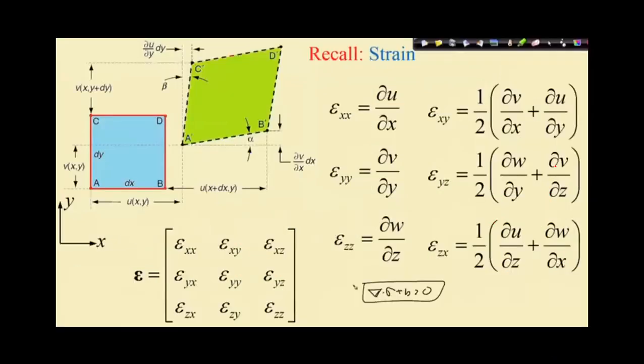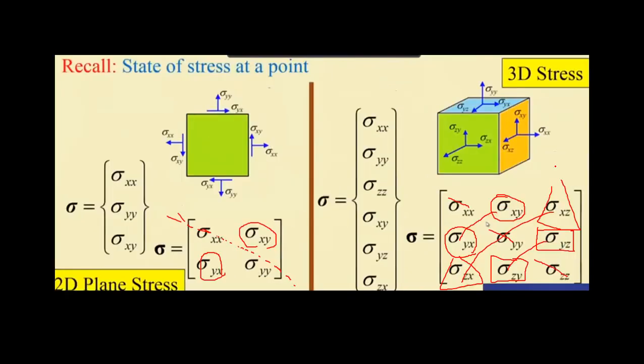And if you consider the strain, the simplest fundamental meaning of strain is the elongation per the original length. That's it. So just consider a bar element. If you apply a force, let's say there's a displacement of delta and the initial length was L, so the strain is delta over L, right? So this is for a 1D case.